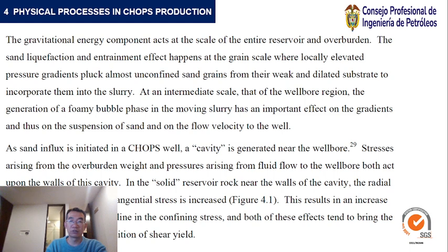In the solid reservoir rock near the walls of the cavity, the radial stress is decreased and the tangential stress is increased. This results in an increase in the shear stress and a decline in the confining stress, and both of these effects tend to bring the intact formation to a condition of shear yield.